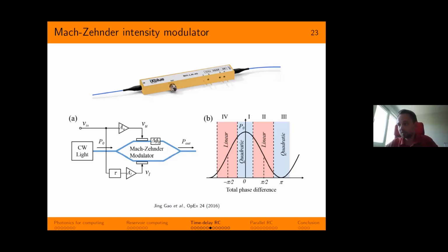Inside the optical modulator, typically made of a particular medium, which is lithium niobate, one finds an optical splitter like this, where the light goes either right or left. And then we apply electrodes either to both arms or just one of the arms. The electrodes allow us to induce a phase difference between the two arms, so that when the arms get recombined here, the phase difference results in a constructive or destructive interference, which acts on the amplitude here at the output